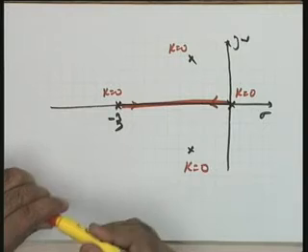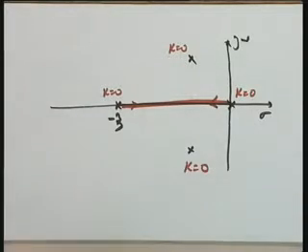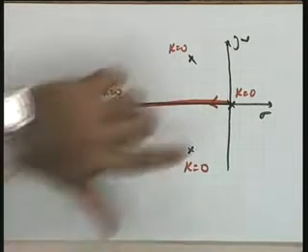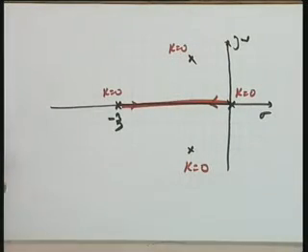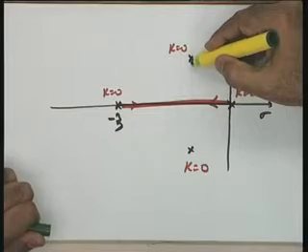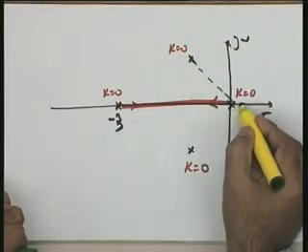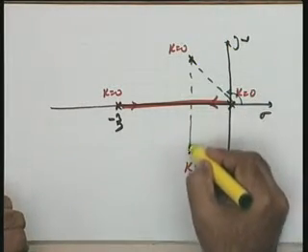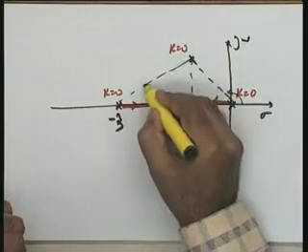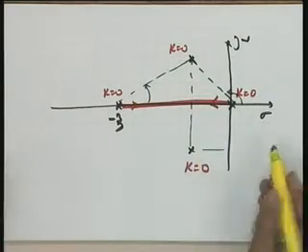This being complex poles, one thing I want is that the direction at which the roots are going to depart should be known to me, because there are so many possibilities, and out of those possibilities one should be set. I may not be applying the rules in the order in which I have given you. Okay, let us set the direction phi p. How do you calculate phi p? Please see, this angle you will take up, this angle and this, and all these will be with negative signs.